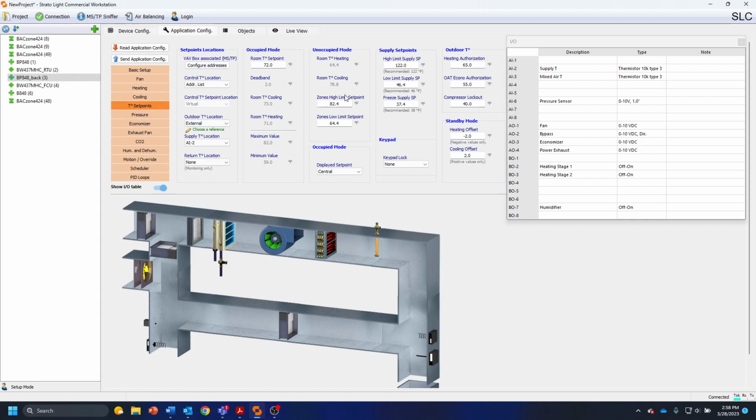And finally, I guess for this, if you're having issues with the temperature reading being way off, things aren't matching up, you're getting things in the hundreds or things are really low, you want to make sure that you don't have any offsets or calibrations that are going to be affecting your temperature readings.